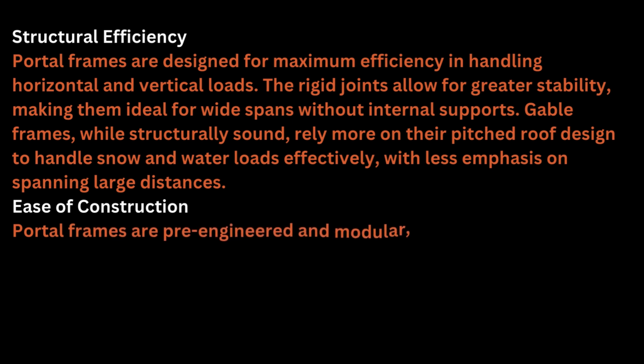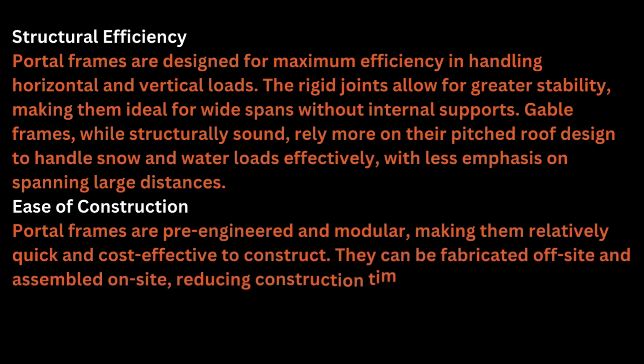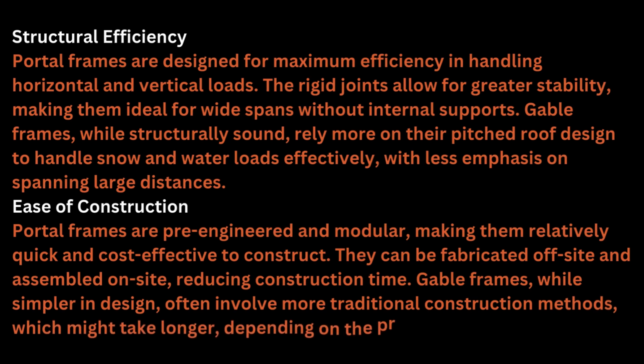Ease of construction. Portal frames are pre-engineered and modular, making them relatively quick and cost-effective to construct. They can be fabricated off-site and assembled on-site, reducing construction time. Gable frames, while simpler in design, often involve more traditional construction methods, which might take longer, depending on the project.